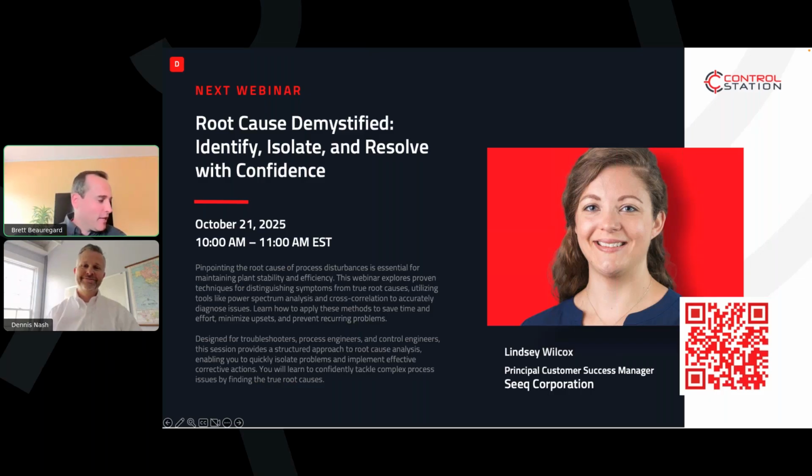It depends, right? Generally, if I have to pick, I'll do something called a doublet test, where we want to get process dynamics. Rather than do a large bump away from where we're operating, I'll go up by a little bit, then down across, and then come back. That lets us get good data above and below where we're operating. But that's a personal preference.